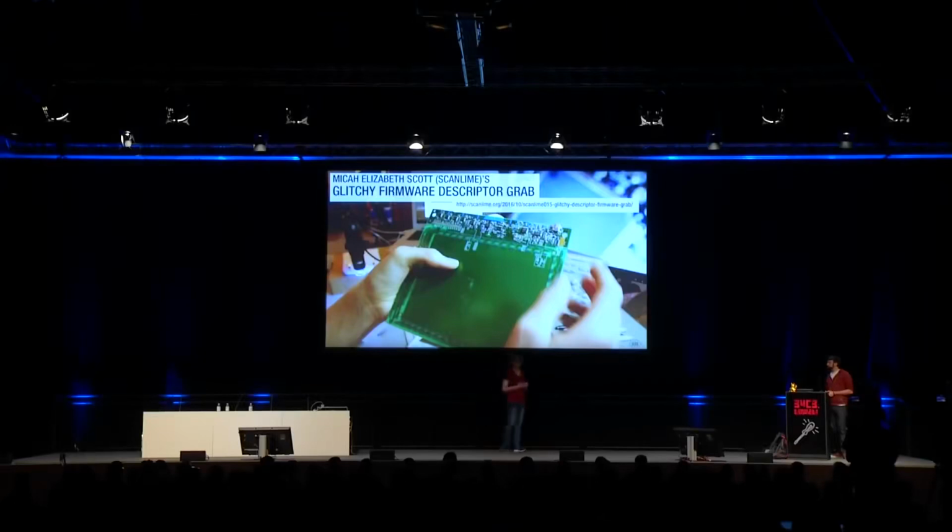of this Wacom tablet. This is the kind of thing that you normally use with an inductive drawing pen, where the pen has no battery, but by holding it close to the tablet, it's able to receive power, modulate its load on that switching matrix, and thus communicate a little bit of information like, yes, I'm a pen, I'm being pressed this hard.